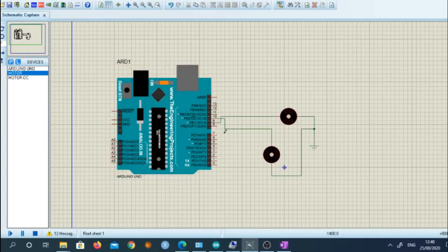You see carefully, pin number 9 and pin number 10, both these two pins are connected to two different motors. Here I will show how to control the rotations or the movement of these motors. In simulation we do not require to power this Arduino board, so this is a very important feature of this simulation. So our advantage, in other words, we do not require any extra power supply or anything here. We need to simply connect these DC motors, and we need to download the program.